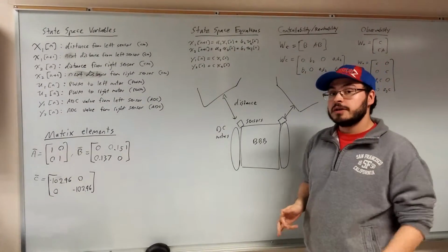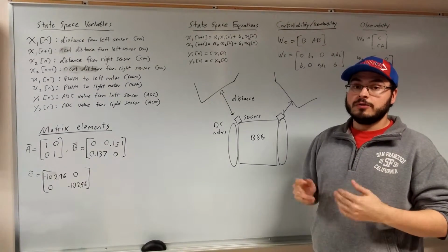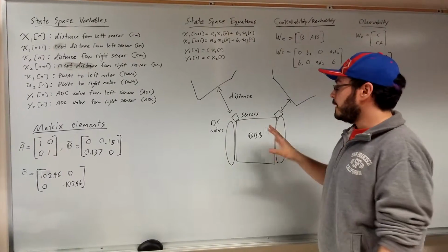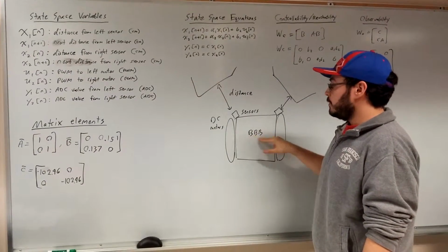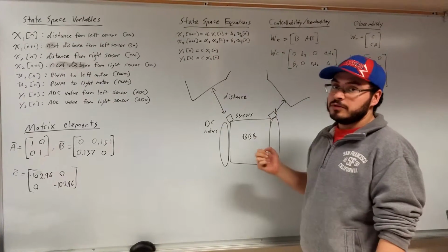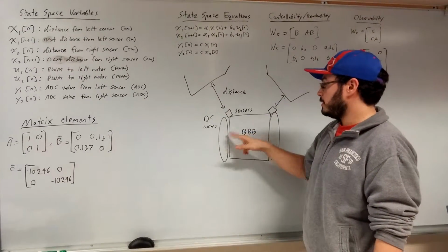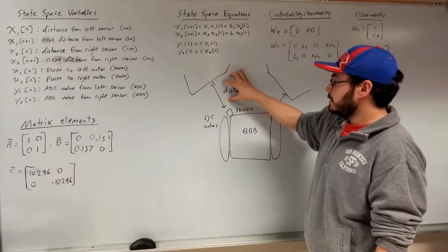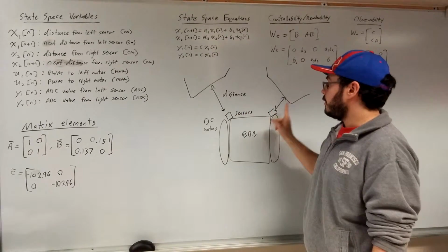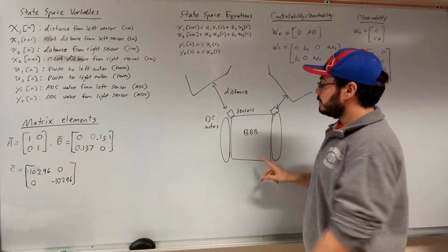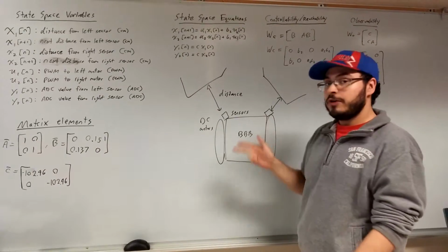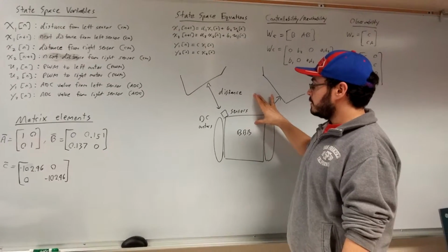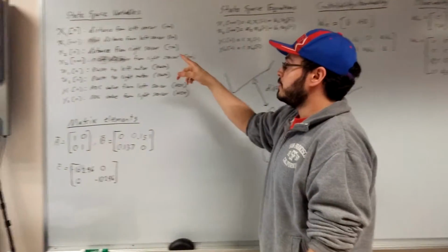For my project, I decided to build a robot that implements obstacle avoidance control using PID control. For the basic model, the robot uses a BeagleBone Black for inputting sensor values, judging distance, and controlling the DC motors. Then it has two IR sensors that judge the distance between an object on the left side and on the right side of the robot. And then it has two DC motors, which of course control how fast the robot moves and whether it turns left or right.